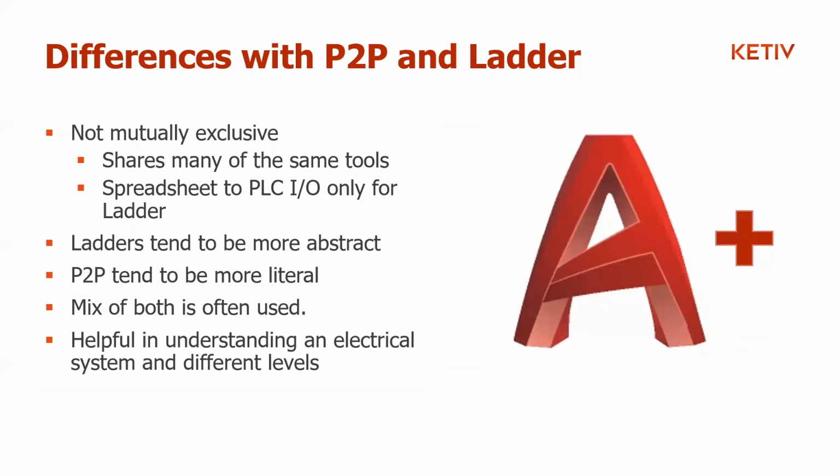Point-to-point and ladder are not mutually exclusive. First of all, let's say that. We get a lot of customers that start off in ladder and then they don't necessarily know how to approach point to point, and so they never really make that jump. But again, they share largely all of the same tools. As far as I know, the spreadsheet to PLC I/O functionality is the only one that's dependent on a ladder diagram setup. But everything else, like the wire editing, component editing, placing, all that stuff, the reference system specifically, those are all largely the same in point-to-point or ladder.